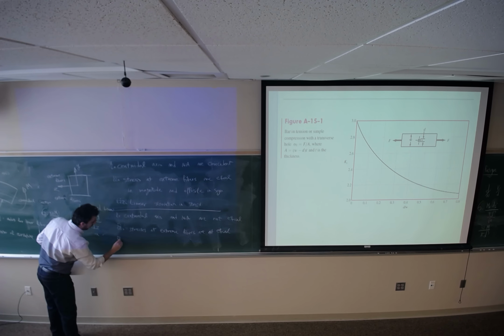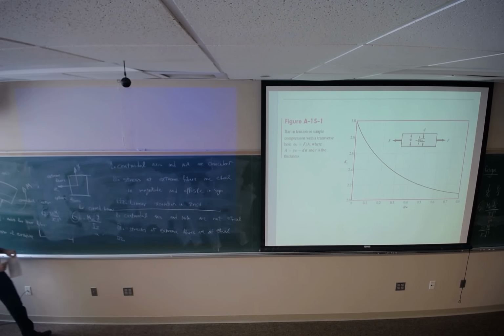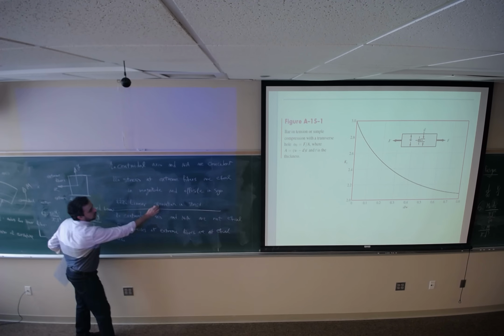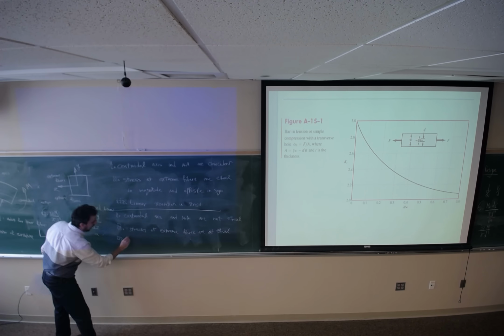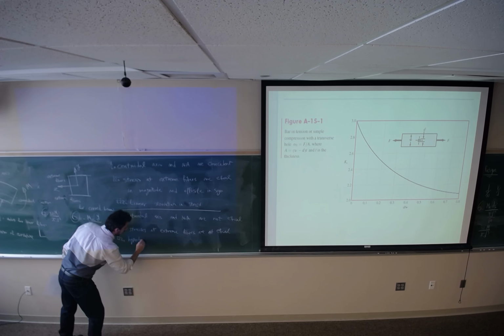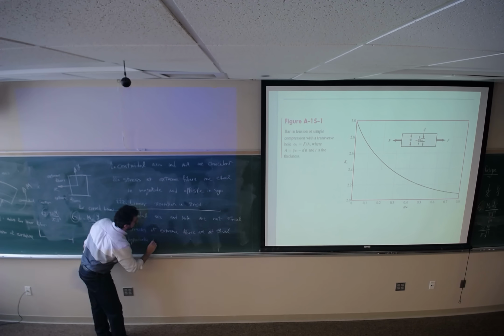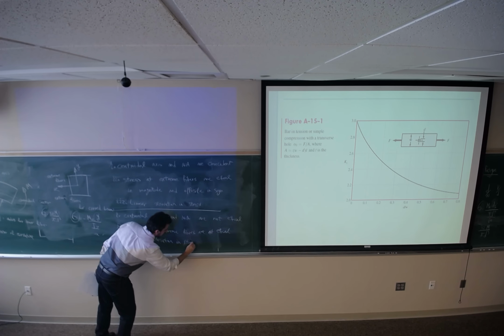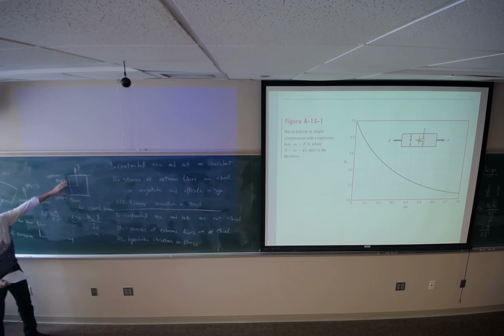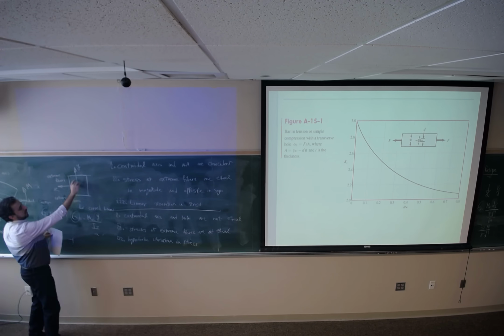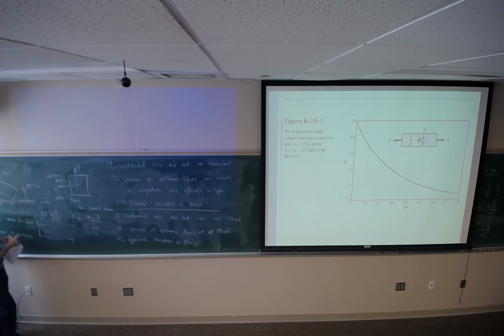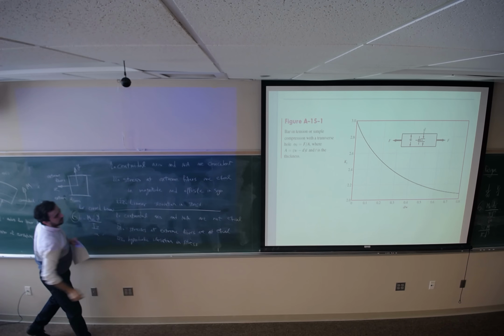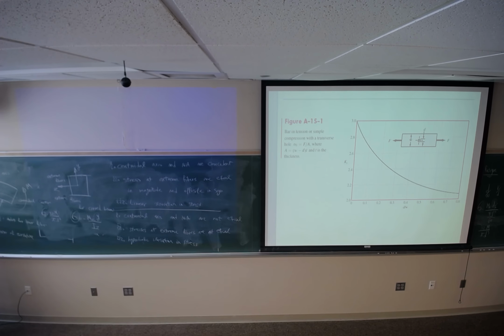Three, we don't have linear variation in stress. We have hyperbolic variation in stress. So in a straight beam, it was varying linearly with the y, but here it's not varying linearly with the y. It's varying as a hyperbolic function over the beam.